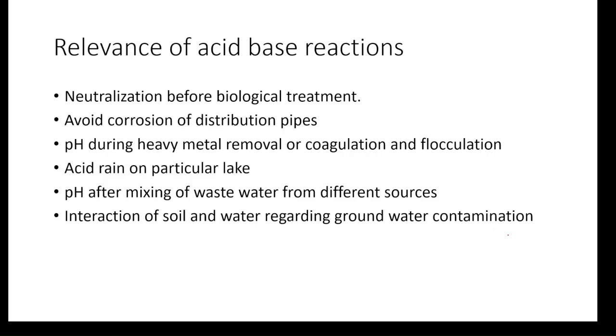So what is the relevance of acid-base reactions? Why do we want to study acid-base reactions? First is neutralization before biological treatment. For example, if there is a pollutant here and I want to degrade it using bacteria, but this bacteria will be most active at pH 7, while the pH of this system is, let's say, 3.